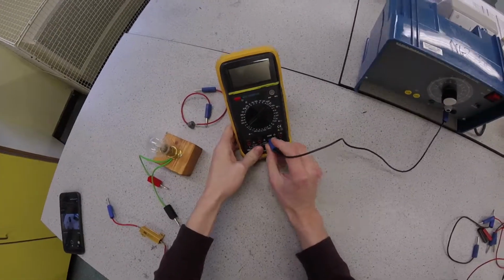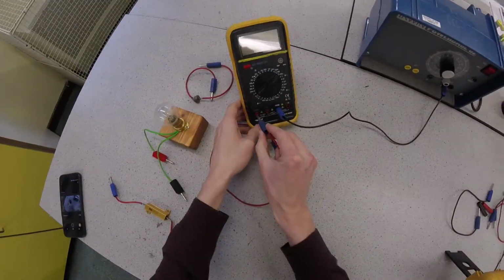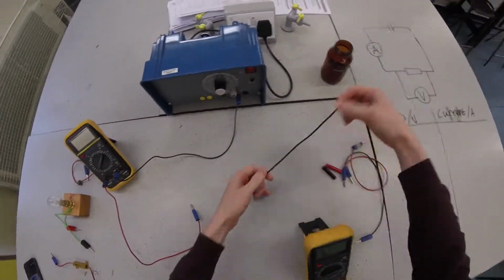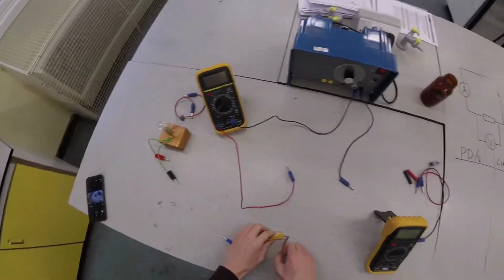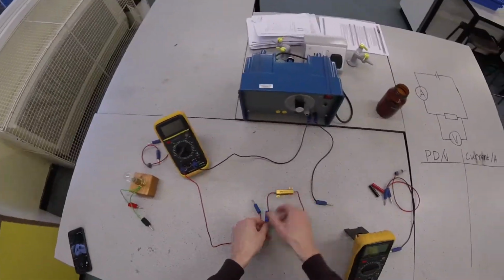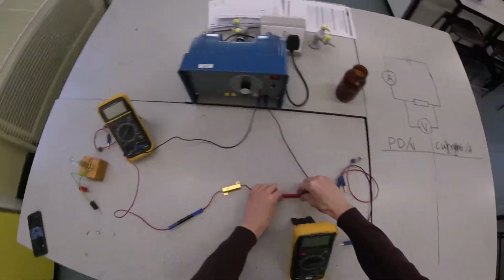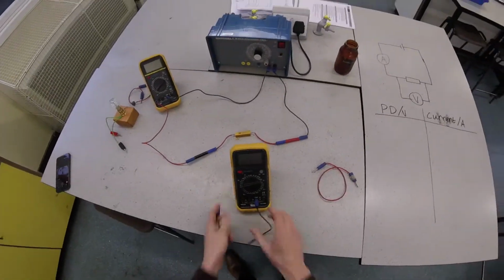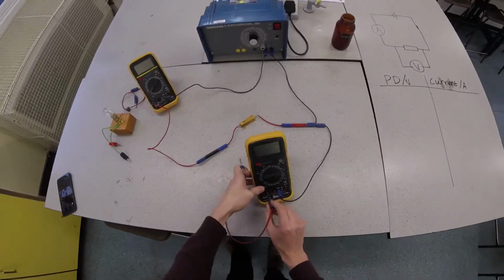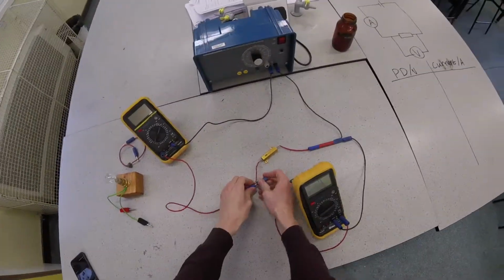Okay, so if you see the setup that I'm going to do then, I'm just going to set up the circuit just like in the circuit diagram. I'm going to start by connecting the ammeter. I'm just going to use multimeters here. So that first multimeter I connected will be our ammeter. There's the resistor, I'm just going to put that in as well, and then across it I will be putting the voltmeter.